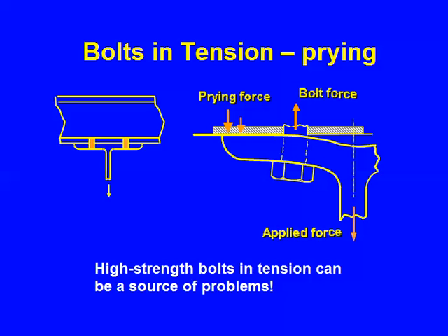There are very, very few problems with bolts. There are disputes and arguments which are usually a matter of interpretation of specification requirements, and some of those issues I hope I'll address this afternoon. Real problems, where it didn't function the way I thought it did, and bad things happened. What's bad things? Fell down, things like that. It's often where we have the bolts in tension, and particularly when there's fatigue. So fatigue, bolts in tension, prying action, that's an area where you have to exercise great care.